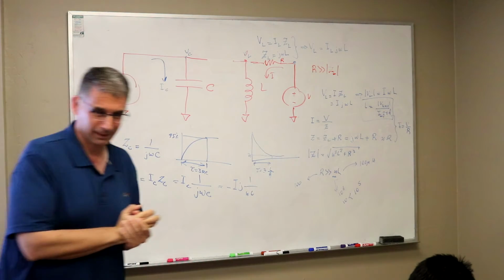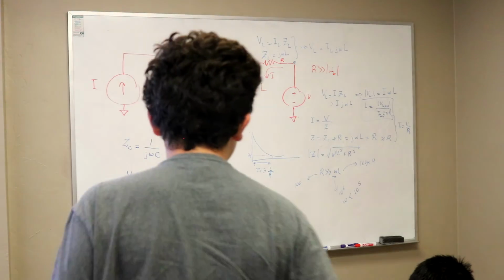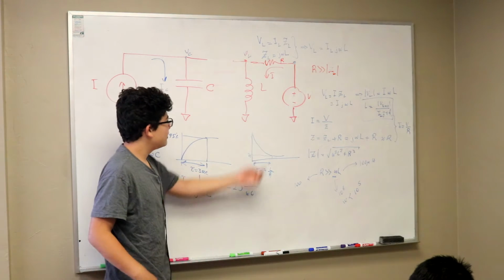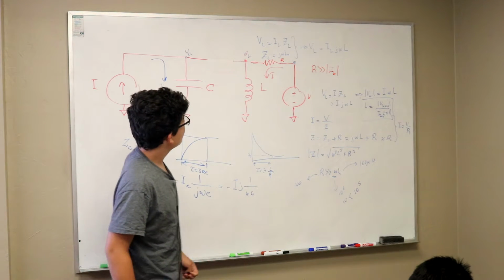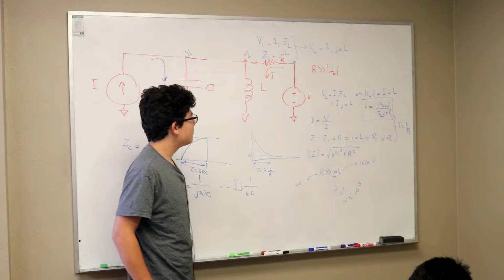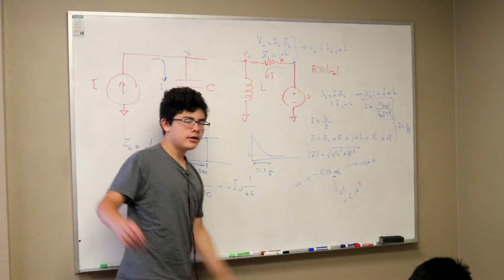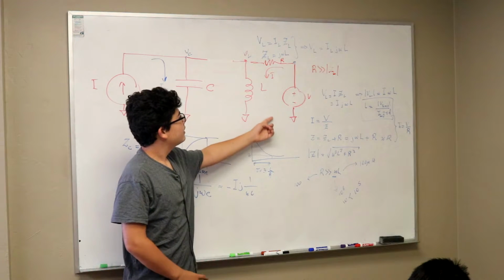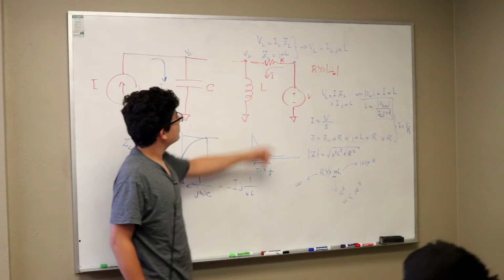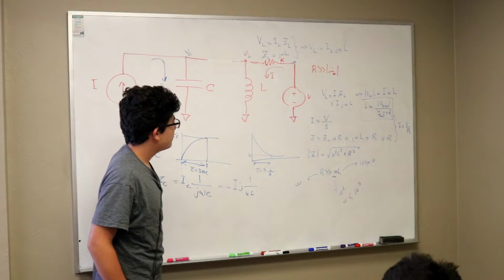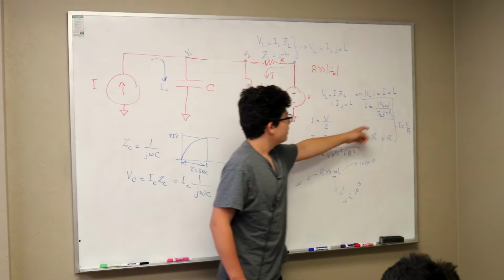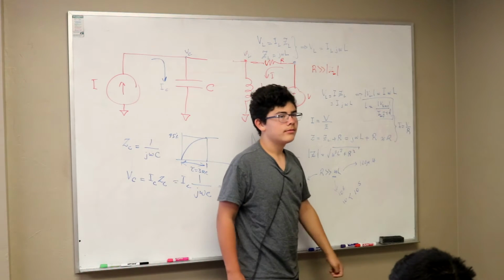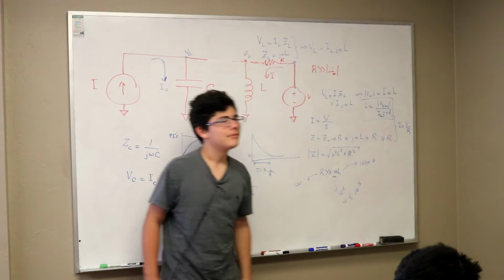We're trying to find the inductance of an inductor. So we're just going to build this circuit, and then through the oscilloscope, we're going to create a voltage. And then put in a 100 ohm resistor, and then we measure the VL max and the I max, and then we find out, right? Okay.